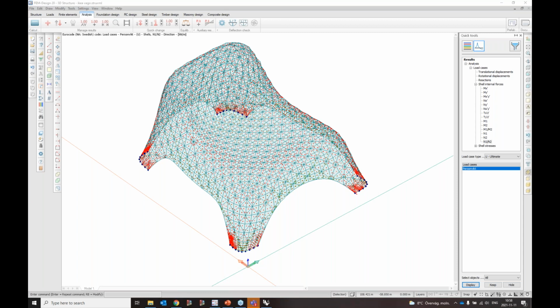Let's see, someone asked, maybe it was asked before, but can we create a plugin add-in for Fem Design? So yes, you can. Definitely. I think that is something that we could talk about in a webinar where we focus on C# and Python. But you could, for example, create a Windows Forms application that accesses your Fem Design model, and you could have some different buttons that the user can press, and it will do different things in Fem Design. So definitely.